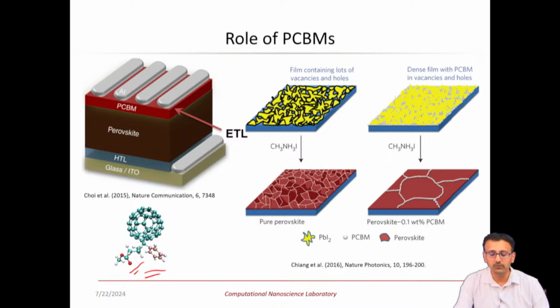So, our effort here was to see if there is a way we can start from the very fundamentals, which is looking at the electronic structure of these layers and identify what sort of defects lead to trap states that are generated in the electronic structure, in the band structure, and what sort of impact they might have in charge recombination, and how we are able to mitigate it by tailoring the processing conditions, such as what temperature we process this at, what concentration the PCBMs should be in the solvent, etc., to get a smooth even layer so that we are able to get the best efficiency.